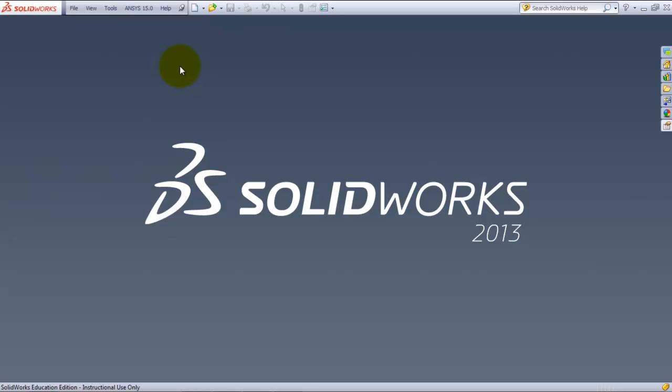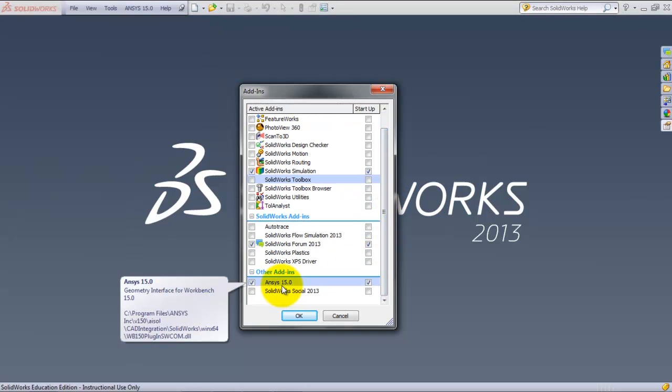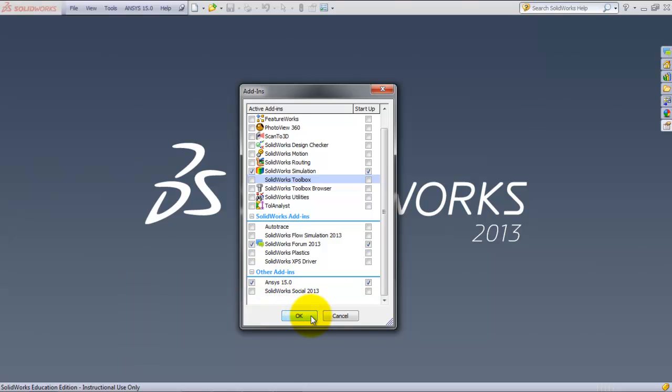You also want to make sure if we're going to use the SolidWorks integration with ANSYS capability, you need to see an ANSYS menu up here. If you don't, it may be because you need to go into add-ins. We'll wait for this to come up, and then at the bottom, hopefully you'll see ANSYS 15. Now, there might be an issue with needing to install it. Once you have SolidWorks, it could be various things that are happening, and so I can't really help you troubleshoot that. But you should see that there. If you don't, there is another really easy way to get around it, but it just makes things a little bit quicker to integrate. So I'll show you both ways, and we'll be good there.